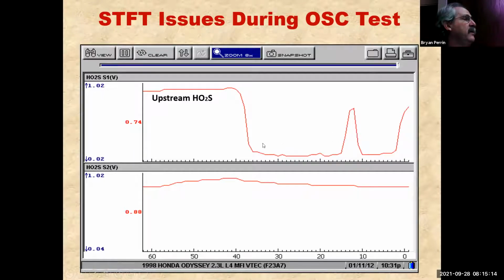On the other hand, is this 1 second of time? If it's 1 second of time, what I need to do is hold the propane longer. I didn't move fuel trim down low enough. That's why we give you that negative 20% number. So if I only move fuel trim down 5%, I got my sensors all high and I turn it off too quickly, it's going to give me a shorter amount of oxygen storage time. And that's why we use fuel trim to make sure that, hey, we've moved it enough so we can get a predictable time once we shift.